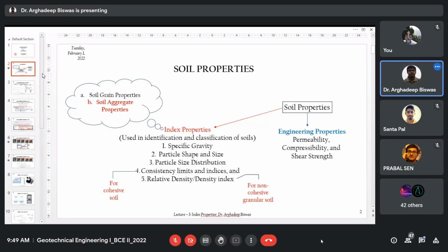Right? So this is the size concept. The size is being measured in our case either as a dry measurement, that means sieve. In case of sieve, the particle or soil mass should be dried. For particles smaller than 75 micron, sieves are not appropriate. In that case, we go for the hydrometer analysis. In hydrometer analysis, we consider Stokes law is valid. That part I will discuss later.